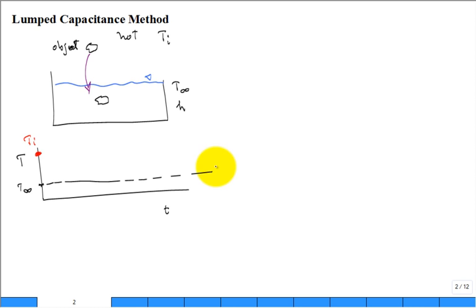What does it do? Does it go like this? No. It's not going to be a linear temperature profile as a function of time, is it? Is it going to be something like this? That's dynamics. You have to have inertia in the system. And what we have in thermal systems, thankfully, nothing with the second time derivative. It's always just the first time derivative. So there's no thermal inertia. It's a lot simpler than dynamic systems. And so what does it do? First order system.